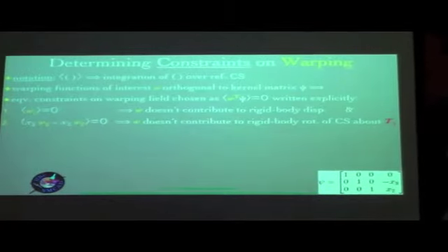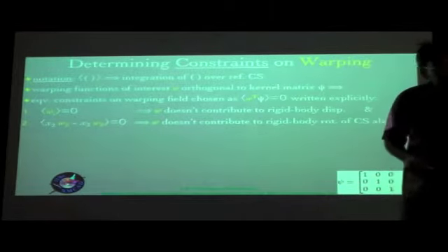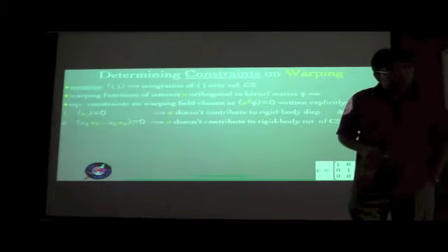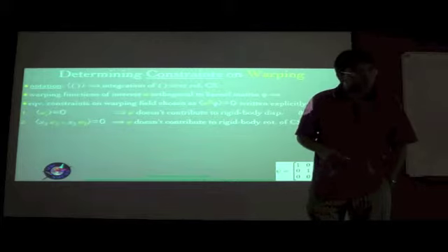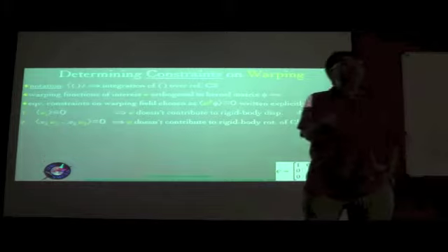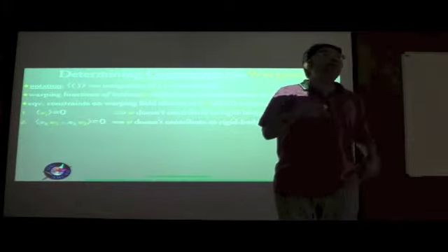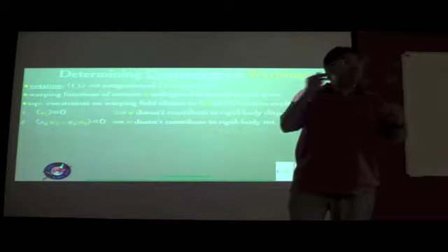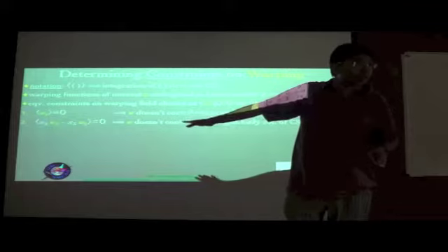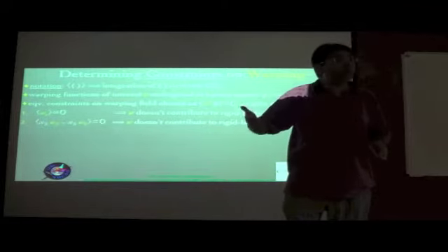So this result is independent of the choice of the reference line. Like if we choose the shear center, the locus of the shear center, as our reference line, or if we choose the centroid. The choice of that will dictate the specific meaning of the 1D variables, for example, and the meaning of the warping itself. But the constraint that you choose is independent of that. Again, as I said, these are not sacrosanct constraints. This is just one way of defining it.